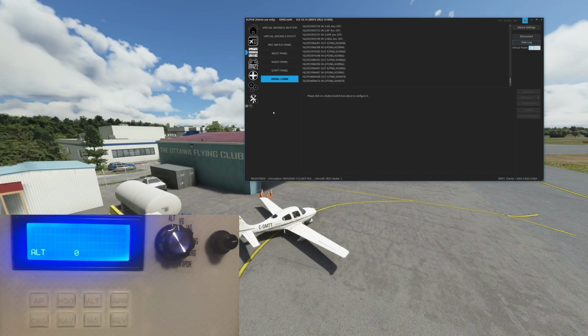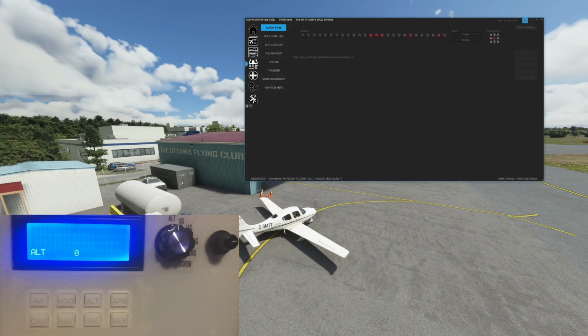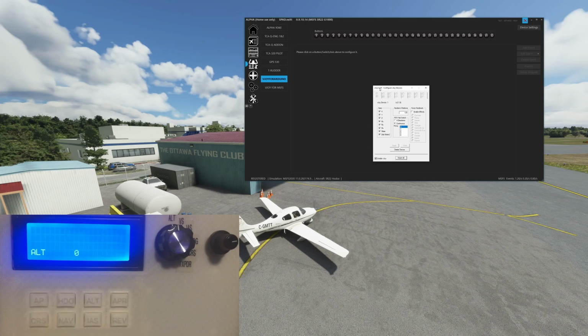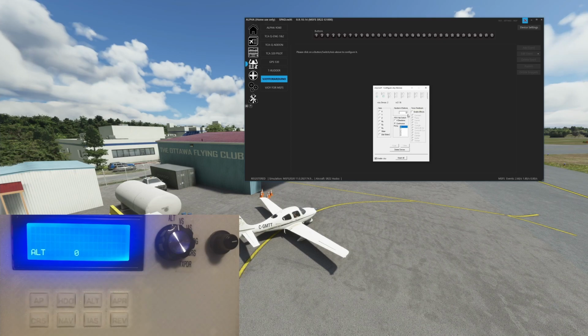As you recall, we set it up so that all the events that we send are going to come in to our second vJoy panel. Now, if you haven't set up vJoy, we have a separate video for it, which you can also find in the list of how-to videos. But looking quickly at the vJoy configuration, you can see that the first one is the one we use for our cameras inside of Microsoft Flight Sim, and the second one I set up to be the device I was going to use with my Arduino. I chose to set it up as 32 buttons and no POVs and no axes, hence it only shows up as 32 buttons here inside of SPAD.next.